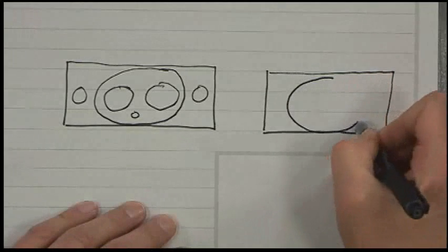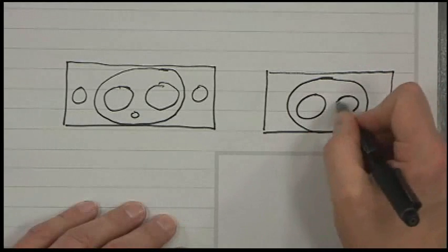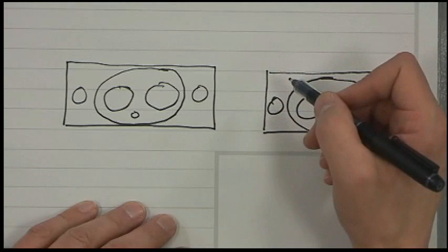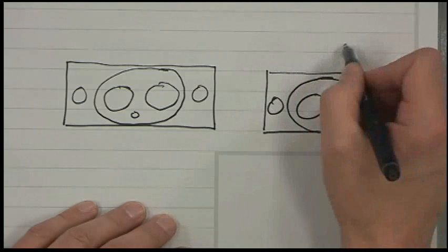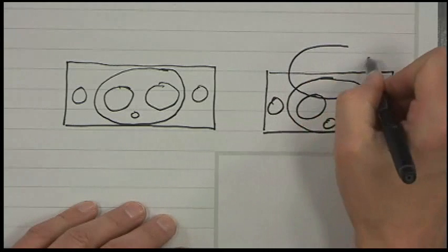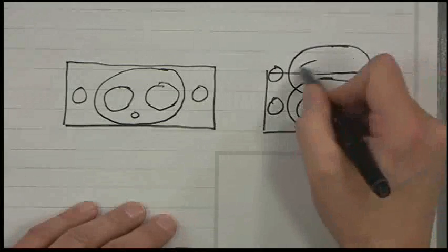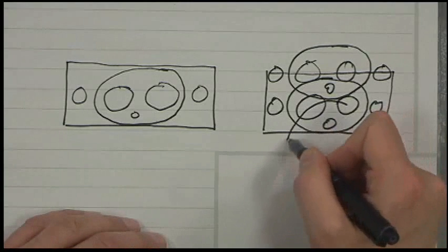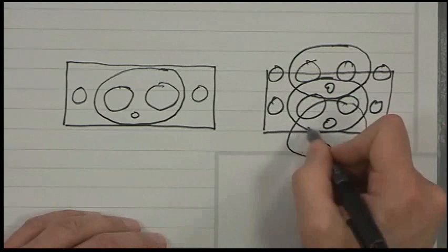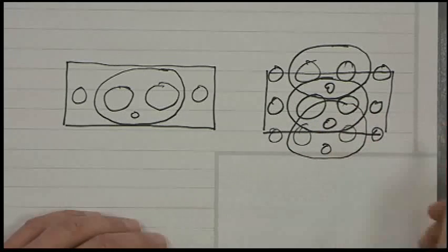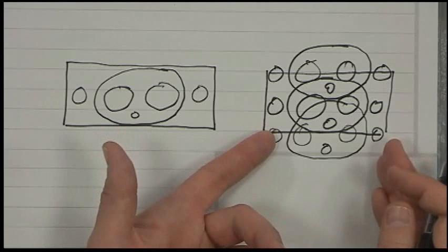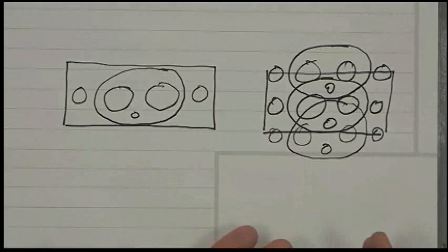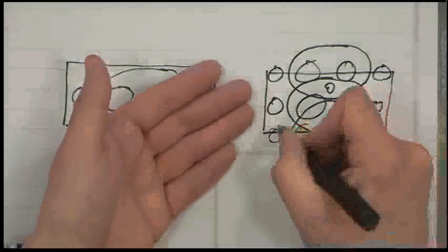If you sample too coarsely, you'll get overlap, and it'll look like this. You'll get the primary image, and then you'll get a secondary version. Let's say you undersampled by a factor of 2, you'll get a secondary version of the image overlaid on it. And you'll get one down here too. So it'll be a confused mess. It'll be like the person was being wrapped around themselves. Okay? That's sometimes called wraparound.